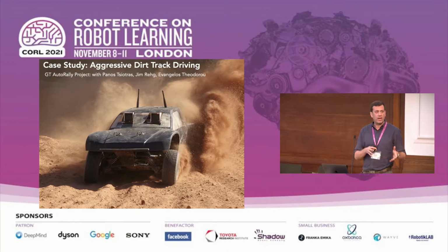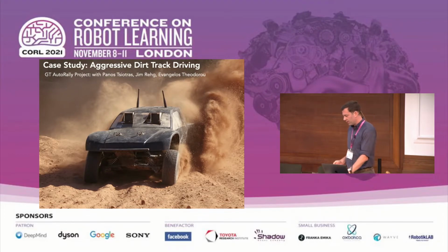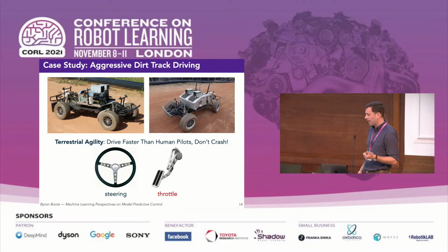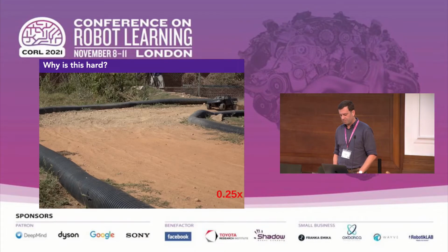It also has considerable onboard computational resources. So we're going to do all of our processing onboard the vehicle so that there's no latency from communication or anything like that, or less, let's say. In particular, it has a GPU on board, which we can leverage in order to make MPC really fast. So we can control the car by modulating steering and throttle. And the question now is, how do we design a policy that will allow us to pilot the car at high speeds over rough terrain?